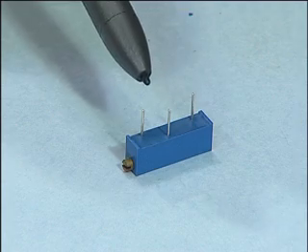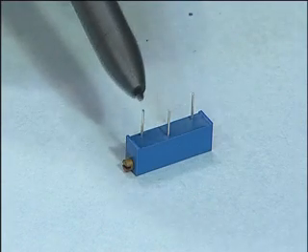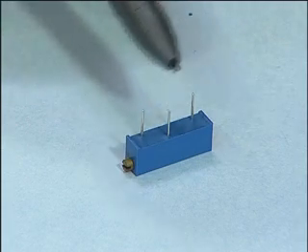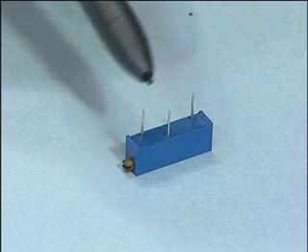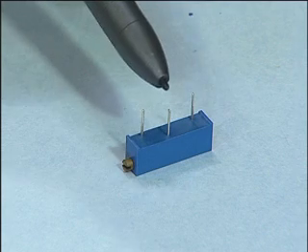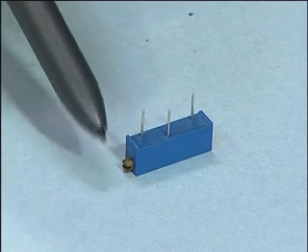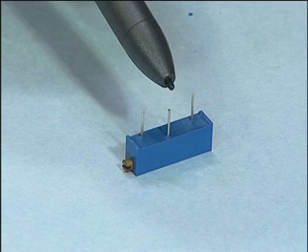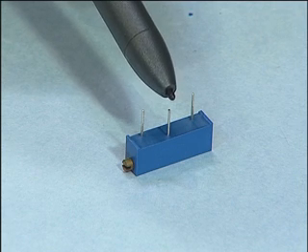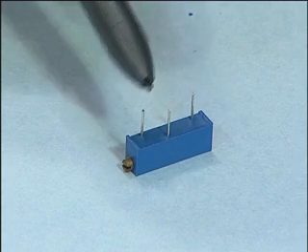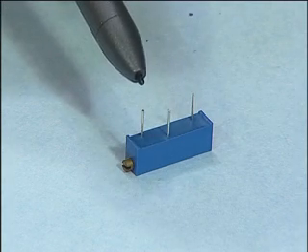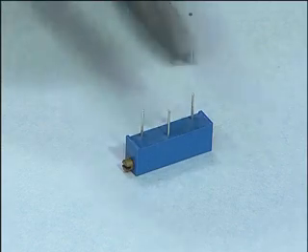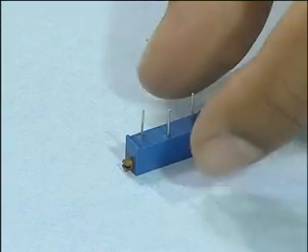There is a screw here which can be rotated to position the center tap at any arbitrary value depending upon the particular circuit. So, if we connect a voltage across these 2 extreme terminals, the voltage across them is going to be fixed, because the resistance across the 2 extreme terminals is fixed. And if we rotate the screw, the center tapped position keeps varying, and the potential of the center tap with respect to the extreme terminals keeps varying. This is called a potentiometer. It is a variable resistor.